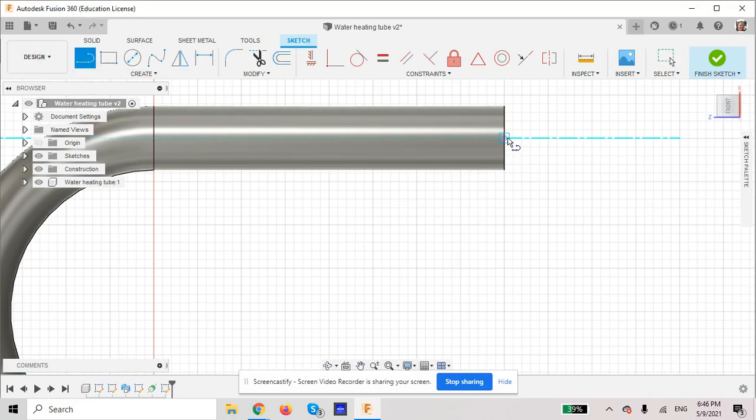I'm going to draw some lines. I'm going to go from here up to the top there, and we're asked to go here and then down, and then go back to our starting point. Now, let me go ahead and dimension. I'm going to dimension from here to this side. We're going to set that to 0.25 inches, quarter inch. We're not really given an angle for this. I'm going to go ahead and say we'll go with a nice round deep angle of 10 degrees. Okay, so that looks good.